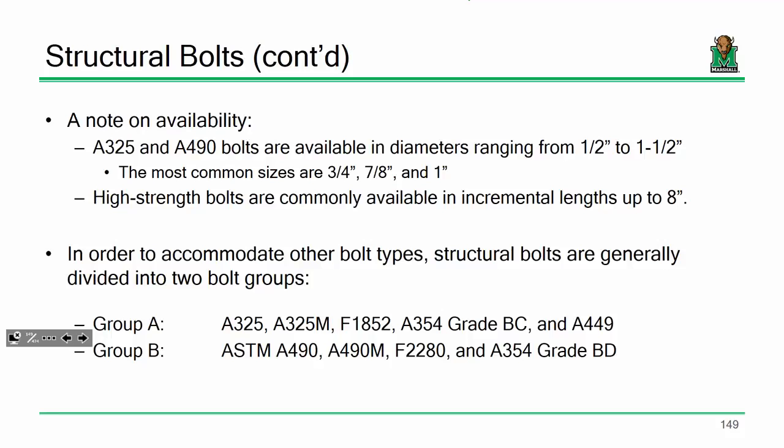All right. Now later on, we're going to talk about the different types of installation methods that you can use for installing bolts, and it leads into 2 different classes of bolted connections that we'll design. We either design bearing type connections or slip critical connections. The difference is that when we use slip critical connections, we're actually counting on that friction that you develop between the 2 plates. And that's really important in 2 big scenarios. Number 1, when you're looking at a bridge, because you always use slip critical connections for bridges. And 2, during earthquake design, because you always want slip critical connections for earthquakes. And they tend to have a lot of demand on them.